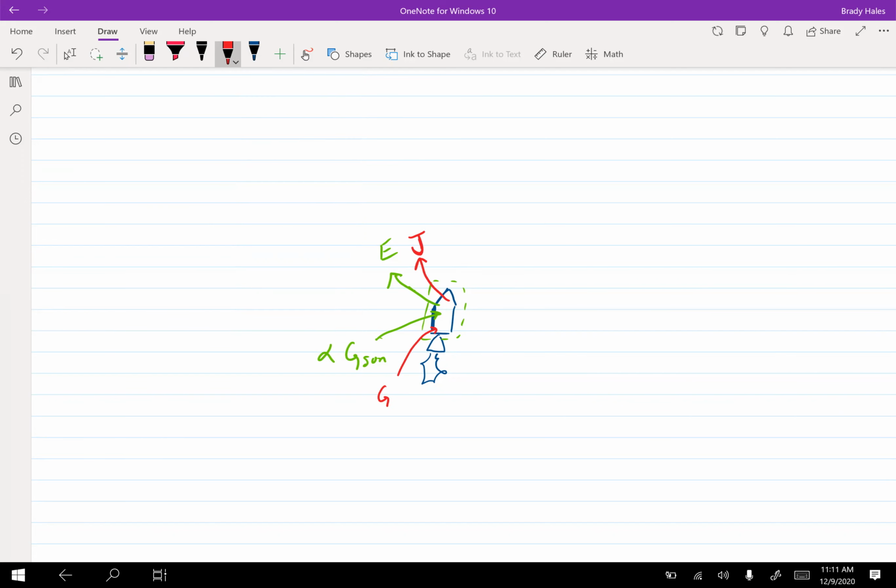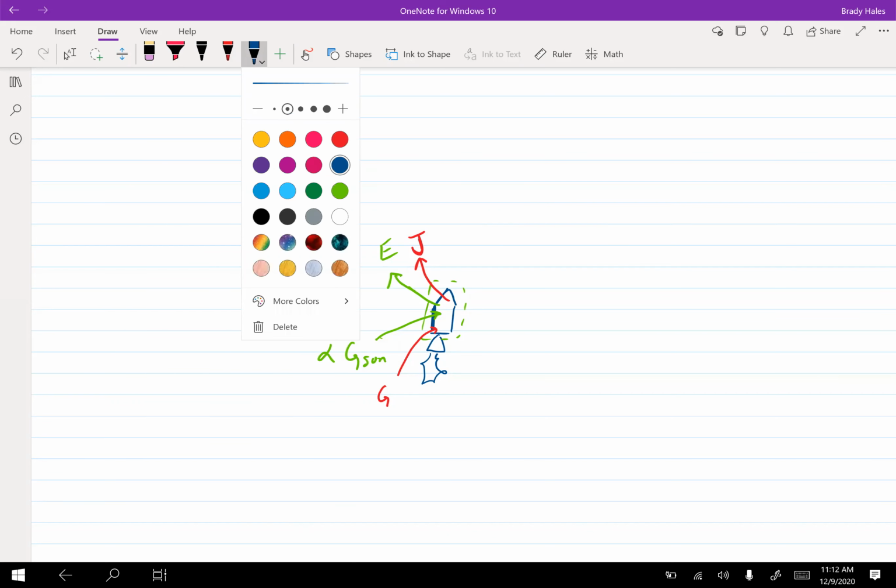Okay, you wouldn't, because J is using reflectivity, right? And remember what reflectivity is. It's 1 minus alpha, right? And in green, I chose to use alpha instead of reflectivity. So you can do green or red. I prefer green personally. I really don't use the specific radiosity term very often.